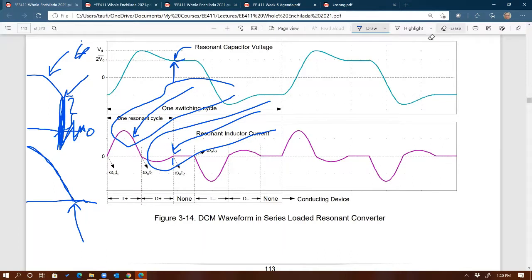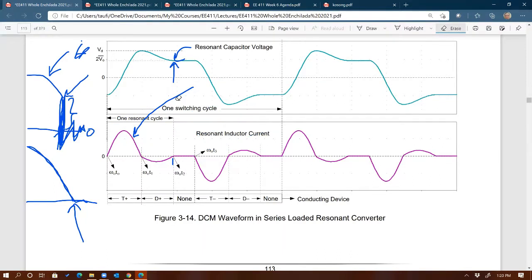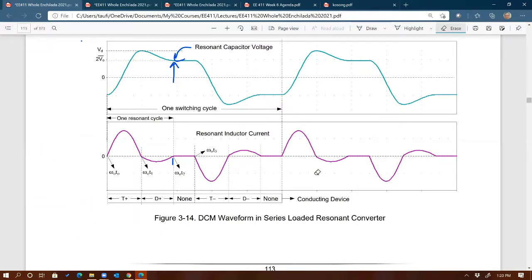And can you guess which mode we used when I worked for that company using this resonant converter? Can you guess which mode? DCM? Exactly, this mode. That's what we use. And there's more benefit, I'll show you later, with DCM. I think it's a very cool mode to operate the converter with. There's also a trade-off, of course, but the benefits you get with DCM are actually a lot more than CCM. Okay, let's see, 5 more minutes.